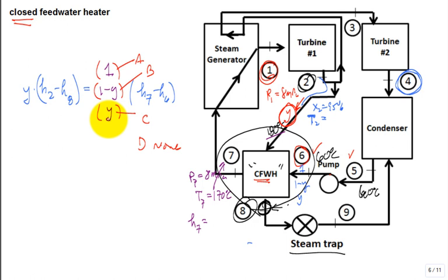Dr. McCorkle? Yeah. State 7, you said, is that a saturated liquid? No. That's a great question. What is state 7? Maybe that's another question for your colleagues. Thank you. I'll ask it in a minute. How do you describe state 7? I won't do it with a clicker question. What is it, though? It's 8 MPa and at 170. The saturation temperature at 8 MPa is 295. The temperature is a lot lower than 295. Subcooled liquid or compressed liquid.